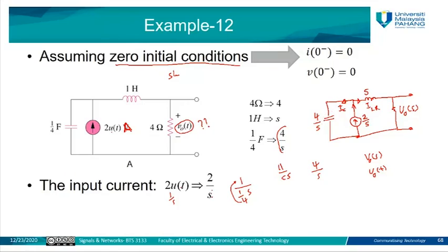So the voltage across this capacitor is equivalent to the voltage across these two elements, which are the inductor and resistor. Because if you apply KVL here, you say VC, we call it VC, the voltage across the capacitor, plus VL plus VR, or V out, is equal to 0, because the summation of all voltages in this loop, clockwise, will equal 0.